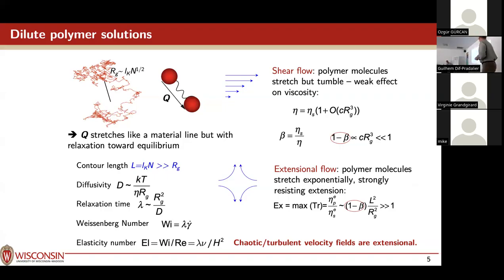Now, in terms of modeling, we are not going to try to model all of the degrees of freedom of this polymer molecule. You can do analysis of this, and the degrees of freedom that correspond to shorter and shorter segments of the chain have faster and faster relaxation times. And in many cases, it's adequate, at least qualitatively, to just model this long chain polymer as a bead spring dumbbell. And the spring here is essentially representing the entropic restoring force. The Brownian motion wants to drive this thing back toward a random coil. And you put two beads here.